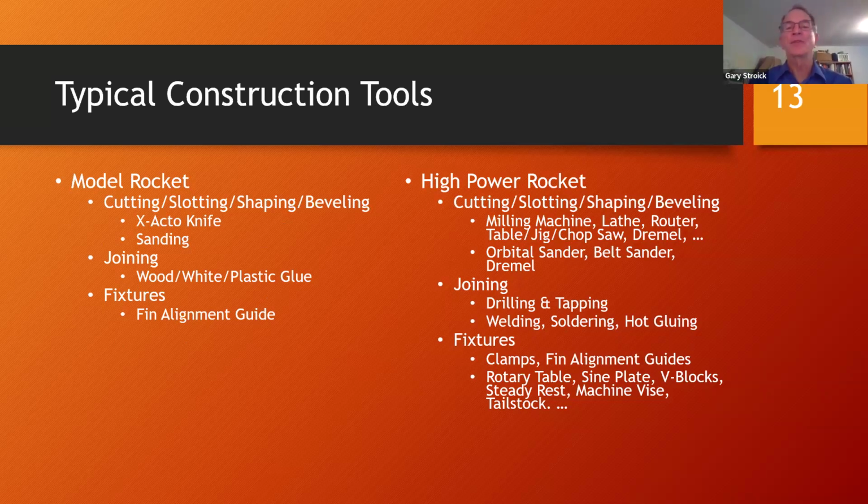So you want to trim that off, and then you want to sand it. And so that's how you shape the fins and bevel the fins, is you would sand these pieces where you've cut off various pieces in order to shape it and get the shape into the smooth and conforming shape with the rest of the component that you're trying to adjust.